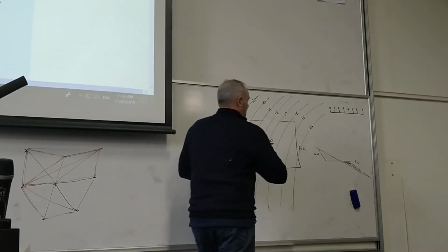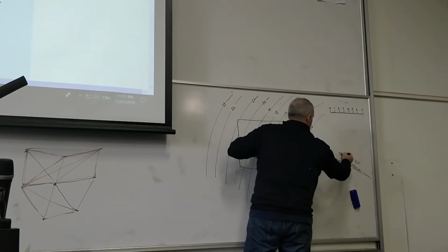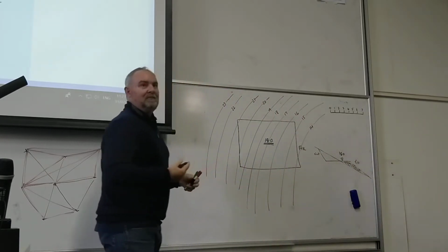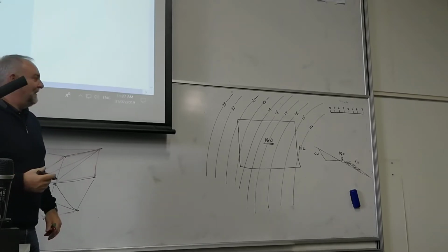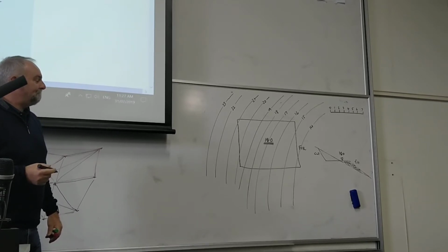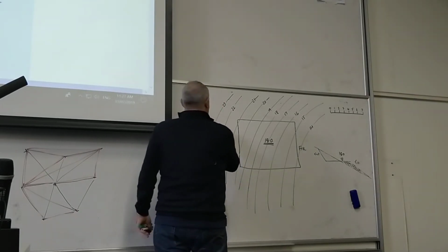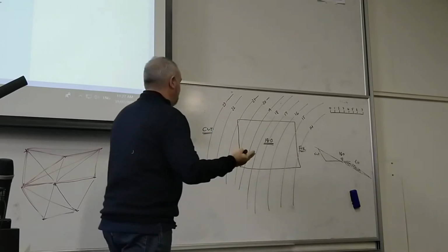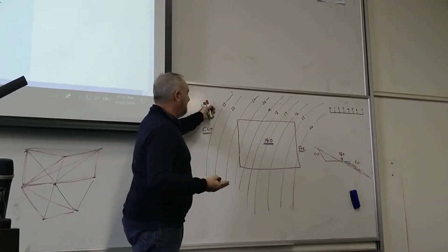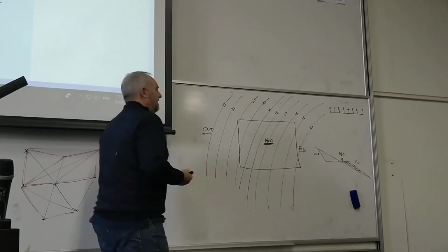So this platform here will be at 18 metres. I'll do my best to move around so my blooming big carcass isn't on top of everything, but I apologise, at times it can be a little bit hard to see. So yeah, cut and fill. Cut over here and fill over here. So when you're doing design, the first thing you do is recognise that the high ones you're going to cut into the back, the low ones you're going to fill it up.